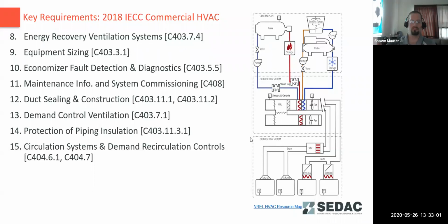Okay, we're going to end our poll here and share the results. Question number 1, what is not an acceptable air barrier material? Looks like most people got it correct, that 1.5 inches of open cell spray foam should be at a minimum 3 inches deeper to qualify, at 4.5 inches to qualify as an air barrier. All those other materials are currently listed as air barrier materials.